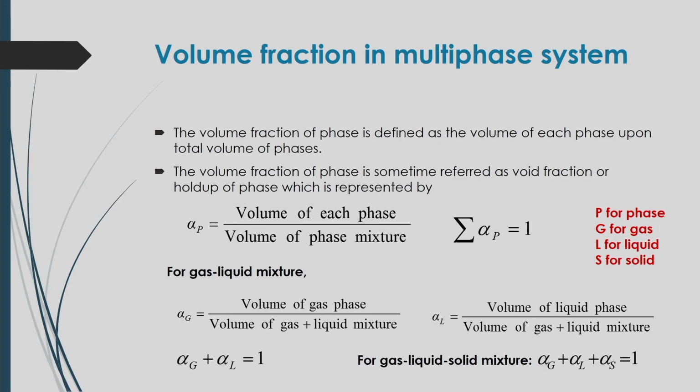Now, individual phases like gas, liquid or solid will occupy certain volume in a particular mixture volume. Volume fraction is defined as the volume of individual phases upon total volume of the phase mixture. So, that will be called volume fraction.